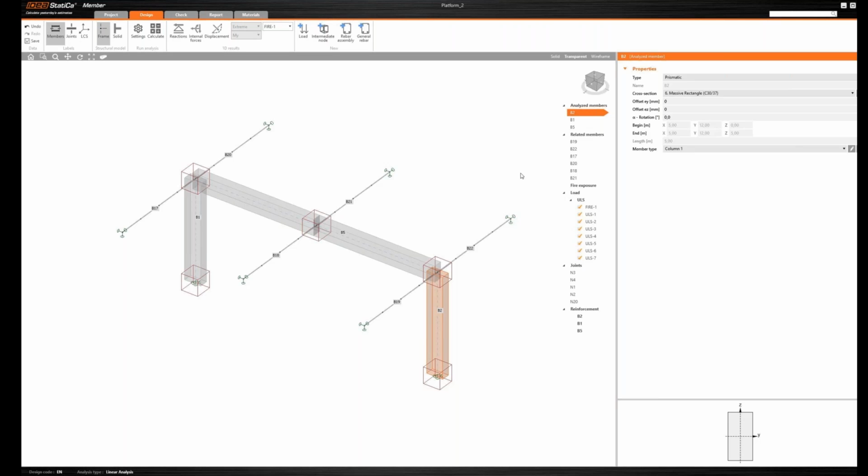As a first step for my thermal analysis, I need to define which of the imported combinations is the one meant for fire design. So I will select combination Fire 1 and wait a little bit for its properties to come up. As we wait, let's note that all loads from the analysis are displayed.